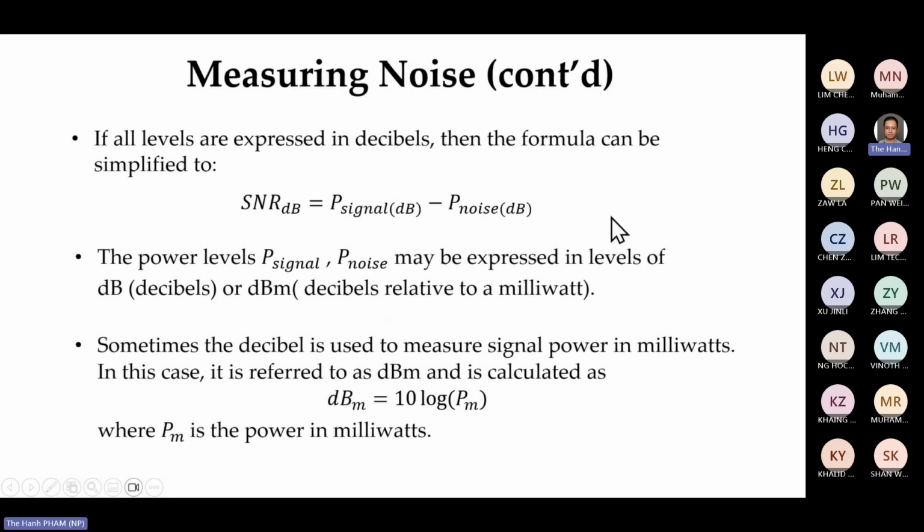You can also calculate it based on, for example, here if you convert power to dB, then the SNR in dB is signal power in dB minus the noise power in dB. Correct. Then please do not confuse between dB and dBm.